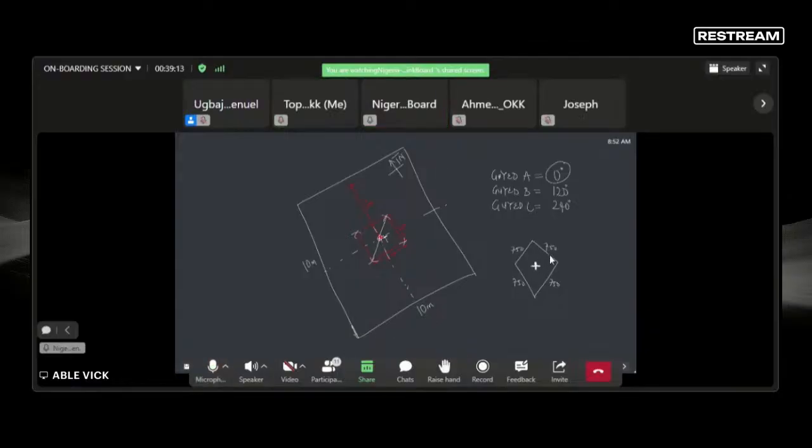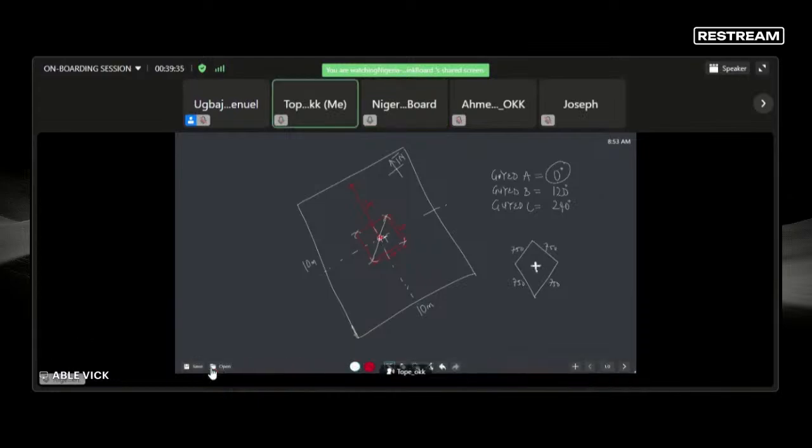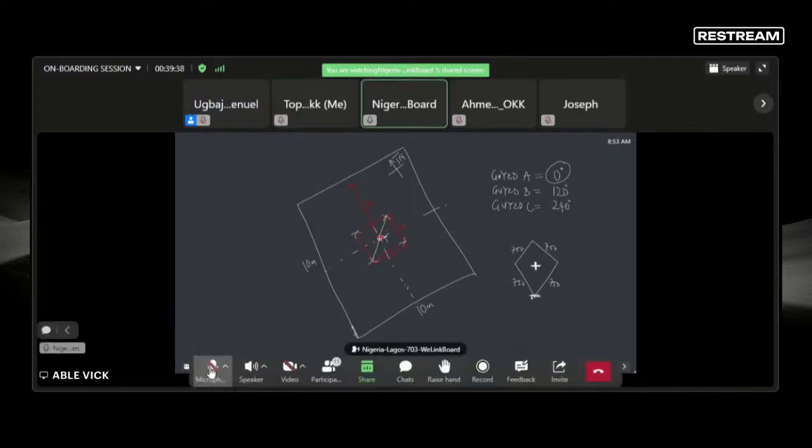That is the exact size of the guide wire base plate. But for the excavation, we excavate more than this. But this is the base plate dimension itself. What I'm showing you is that the 5 meter is stopping at the middle of this base plate, not at the edge here. If you stop it at the edge here, it is wrong. This one is wrong. This is correct.